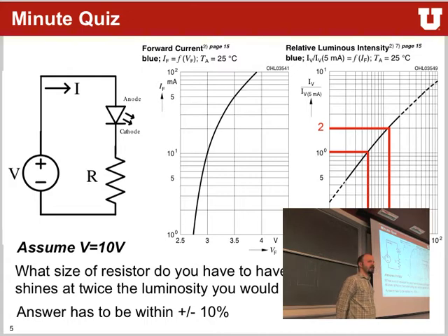I see lots of blank stares trying to figure out what's actually going on here. Who tried to solve the equations for their LEDs on their boards and actually size the resistors appropriately? Some of you? Because I looked at some of the submissions and many of them just kept it at the 1K default value. At 1K, the LED probably will barely light up.